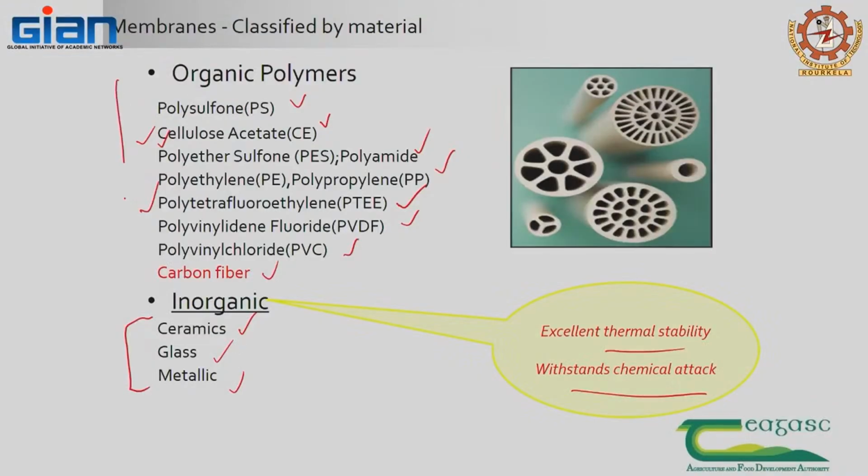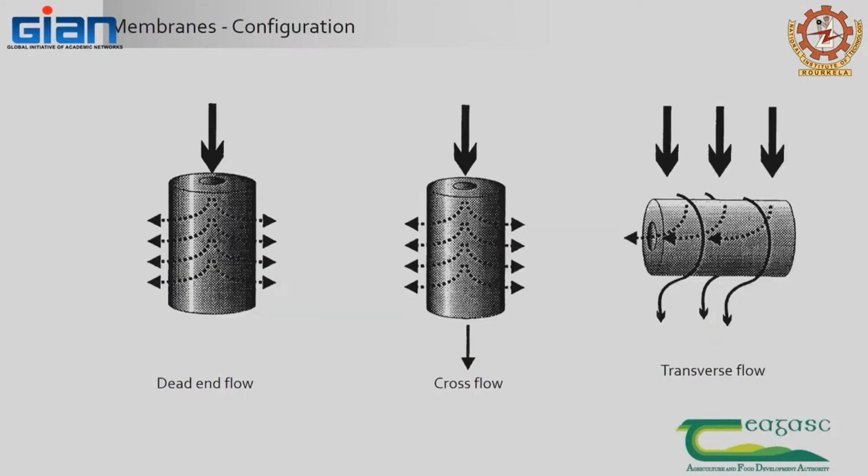There are two things: the material and your biomass. You cannot use a cheesecloth to filter acid with other substances. Repeatedly using hydrochloric acid will damage those fibers and the gaps may increase in size. That is why selection of membrane has certain criteria which we will cover in the next few slides.